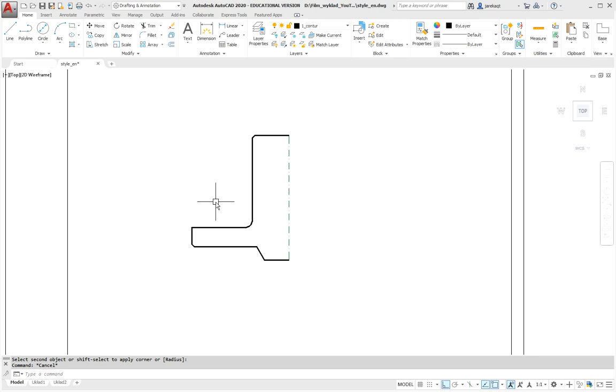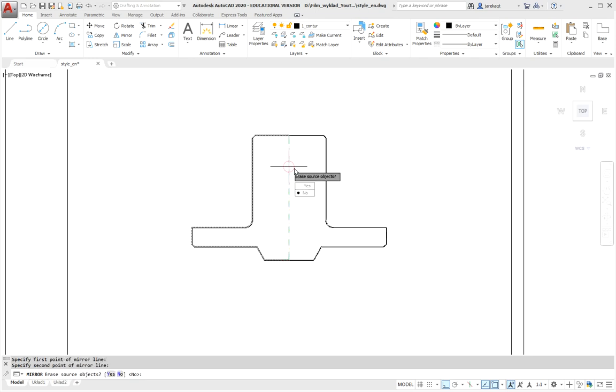On the other side there is exactly the same outline, therefore we will not draw it a second time. We just say that we want to reflect this line in the mirror and enter. We still need edges here, which we must complete. Let's draw a polyline, and on the principle of perpendicular and escape, right key, perpendicular and escape, right key, perpendicular and repeat, and again we have the left side practically finished.